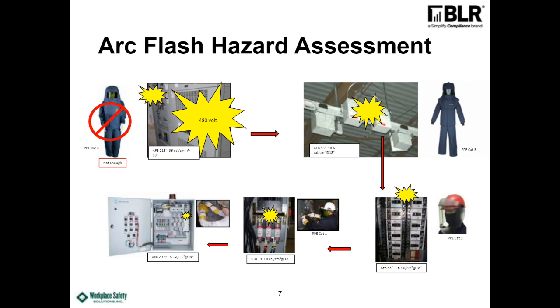You don't have to have a cotton cap. You just have to have, if you're going to wear a cap, it needs to be cotton, not polyester. Because you don't want any meltable fibers around anything to do with any arc flash, because it will melt and it will get right into your skin and have to be surgically removed in some cases.